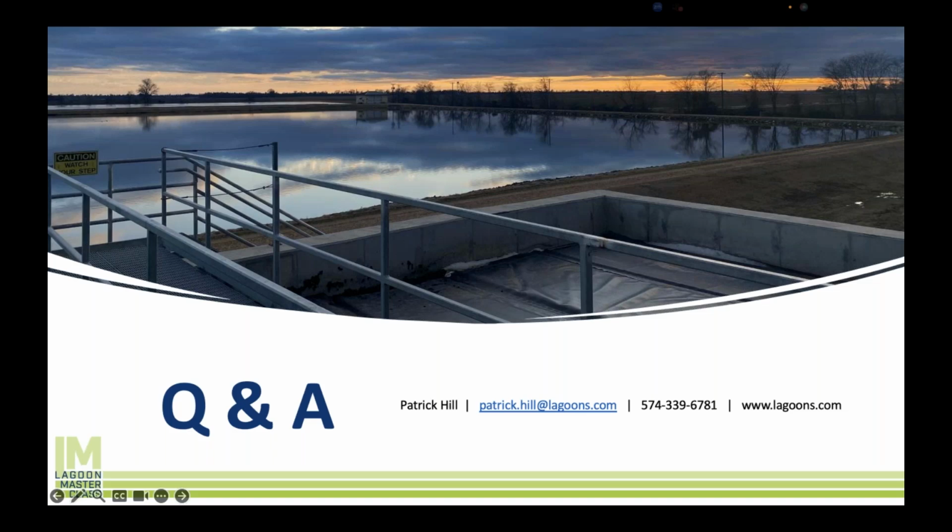I think just logically, it makes sense to me to do phosphorus precipitation after ammonia removal, partly because of what we've seen with our reactors that are after the lagoon at the end of the process. We see breakdown of BOD in those reactors, and we either see a reduction in TSS or in some cases a slight increase in TSS. And to use the precipitant to take out both the phosphorus and the solids at that point, after the reactor, seems to make a little bit more logical sense.